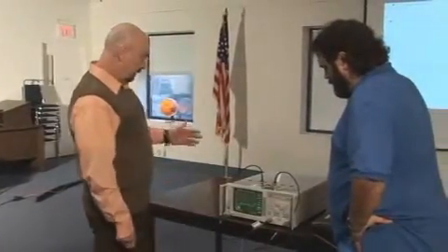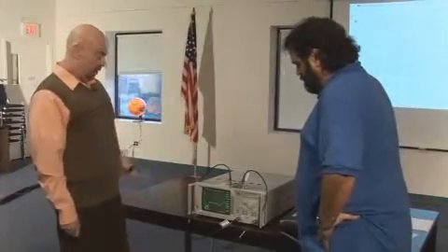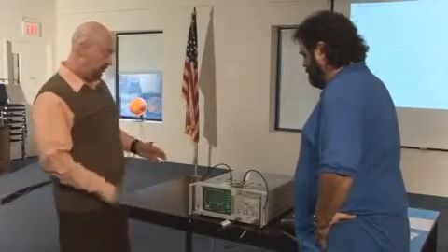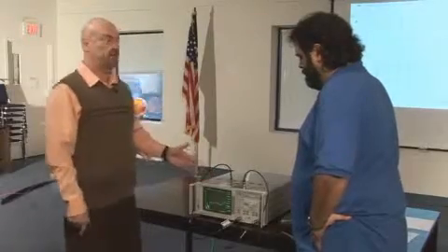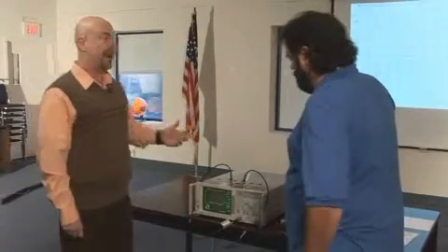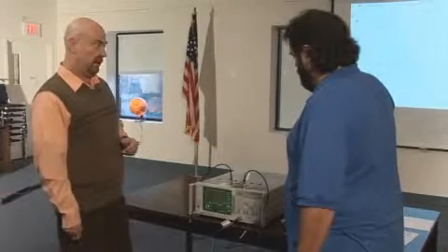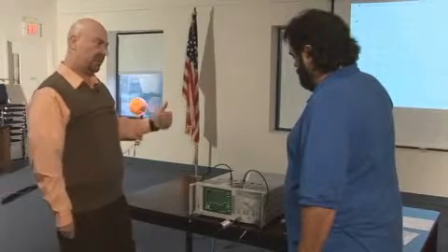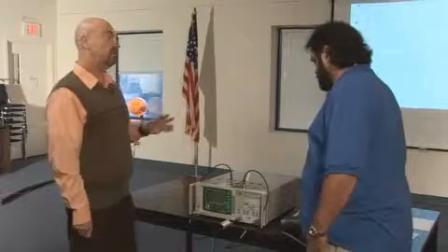Absolutely. All right, well, what I got here is a standard network analyzer. What this does is it measures the transfer characteristics of devices, puts out power through one port, and reads it into another. Typically, a lot of times you'll hear these referred to as scatter parameters. What we'll be looking at today is what's called S21. We'll be putting power into the unit and reading it through it out to the other side. We'll kind of get an idea of what our devices are doing to our signal.